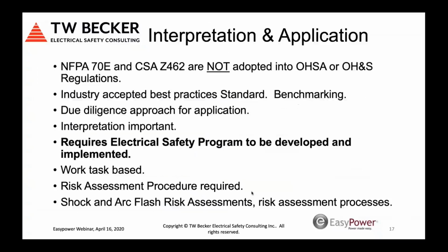So moving into interpretation and application, a little sidebar again. These standards are not adopted into occupational health and safety related legislation in the US or Canada. They're industry accepted best practices, and really I use the word benchmarking. At this point in time, especially in Canada, let alone the US, if you're not using 70E or Z462, your competitors probably are. So it's in your best interest to apply these documents to arc flash and shock hazard management for your company.